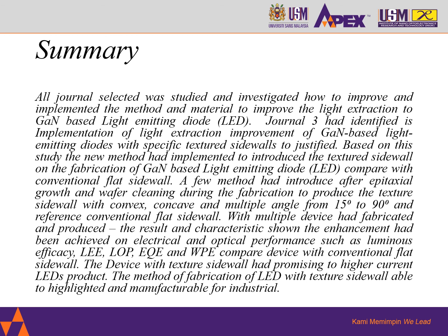A few methods also have been introduced after epitaxial growth and wafer cleaning during the fabrication to produce the textured sidewall with concave, convex, and multiple angles from 50° to 90°, compared with the conventional flat sidewall.